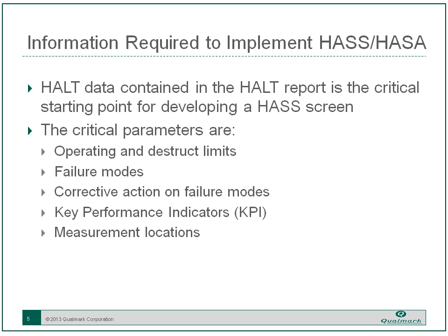Operating and destruct limits, failure modes, and key performance indicators can all help in determining HASS profiles once you go into setting up for HASS. But that is not the only information you'll want from HALT. Based on the results from HALT, you'll be able to perform root cause and corrective actions, which can be taken to improve on the product.